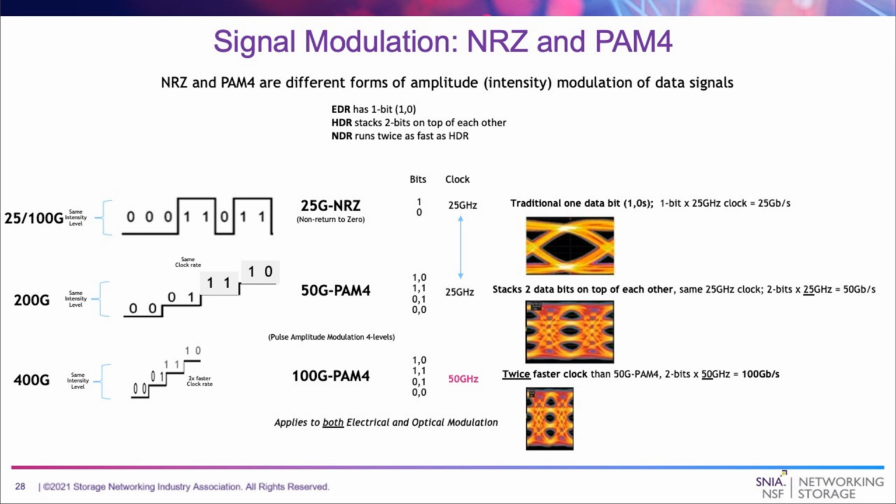If you look at the signal eye diagrams on the right, it's getting pretty tough to pick out the data from the noise. It's just getting to be a big blur. So a lot of the electronics has moved from just a simple clock and data recovery circuit, which might take less than a watt and a few nanoseconds to get through, to using a digital signal processor, which is actually a microprocessor to sort out the signal and run algorithms against the data. So it's getting much more complicated.